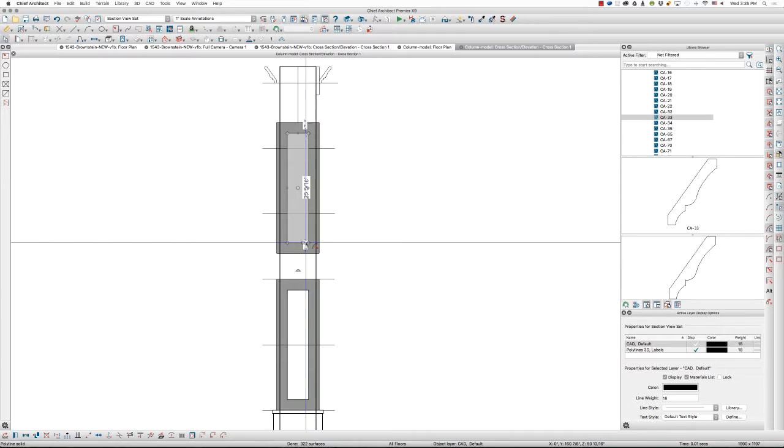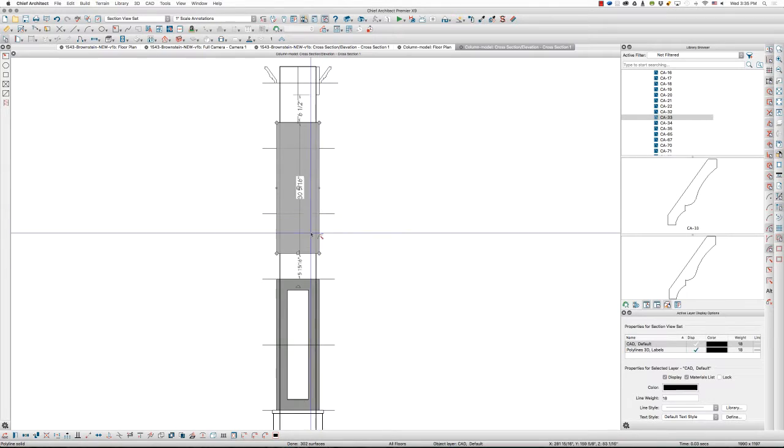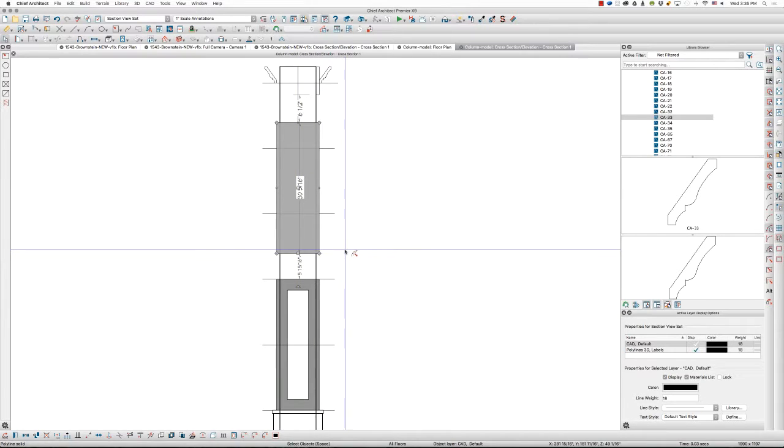What I probably should do right now is actually just delete this hole, because I need to position this piece at its proper dimensions before we make that hole 2.5 inches concentric, right? So if I do my concentric, you can see the mouse cursor has the 2 arcs with the arrow.